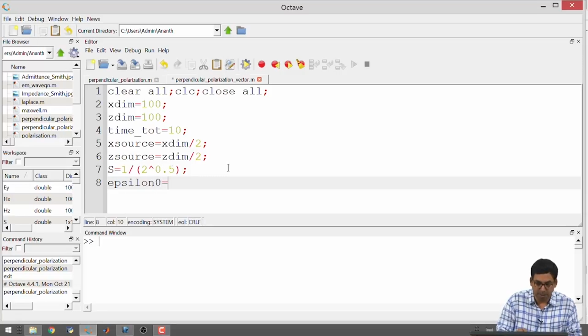So, once again we are using relative units. What we are trying to do here is we are setting the permittivity and permeability of vacuum to 1, just like yesterday, which means that the velocity in free space or vacuum will be considered as 1, and everything else will be considered with respect to the velocity in air. This is done so that you do not have approximation errors while doing some updates, because it is a very tiny number, all right.